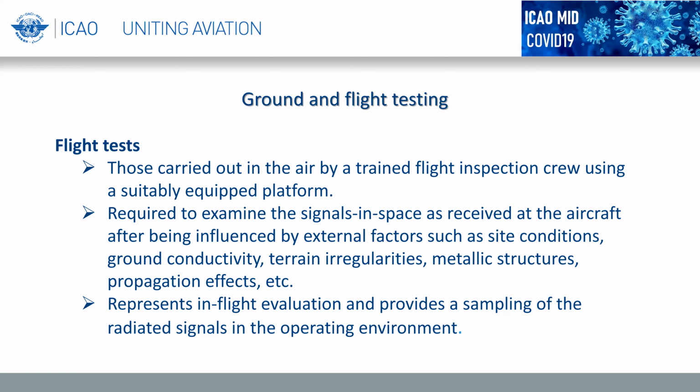While flight tests are carried out by a flight inspection crew, they are required to examine the signal in space as received at the aircraft after being influenced by external factors such as terrain, site conditions, etc. So flight test is the in-flight evaluation of the radiated signal.